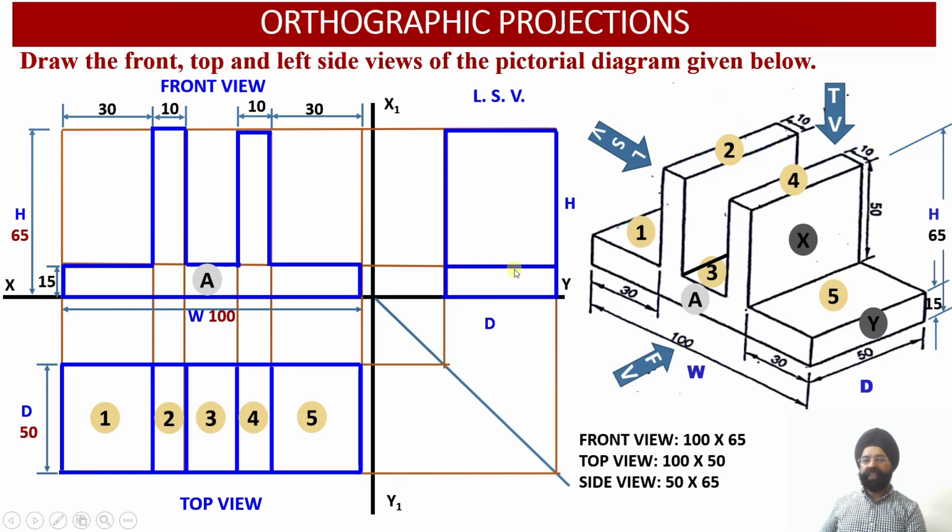Once we draw this edge corresponding to the top surface of this particular low block, you can divide this total side view into two parts. The first part is surface X, which is lying on the other side. This surface is not this surface. This surface is lying on the other side behind this wall over here. And this is my surface Y.